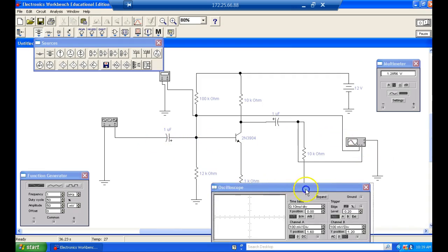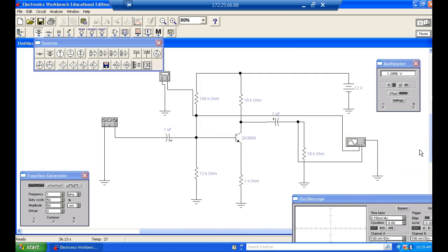We're talking about stereo amplifiers, but the problem of an amplifier is we want to get what type of gain out of these things? Power gain. So to get a power gain, we're going to have a source for the signal, and every signal source that I know of is basically high impedance, right? And then we're going to have to eventually go to a low impedance output to get the power out. So we go through stages in an amplifier. Used to, you could actually see them.